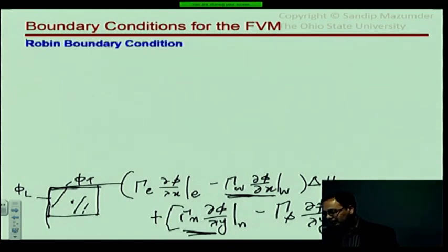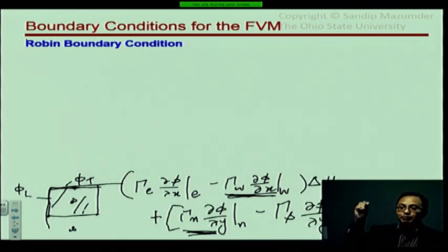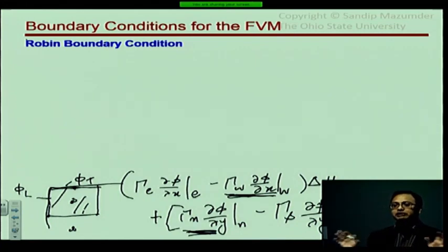And then for the northern face, I'm going to do Taylor series expansions of this about that face and then this about that face, and I'm going to get almost an identical expression as I got for the western face, except instead of k and k plus 1, I'm going to have k and k minus n show up. And instead of phi west or phi left, I'm going to have phi north or phi top in that expression. And then that will go in here. And then after you've plugged those two expressions, you rearrange your equation and you have your nodal equation.